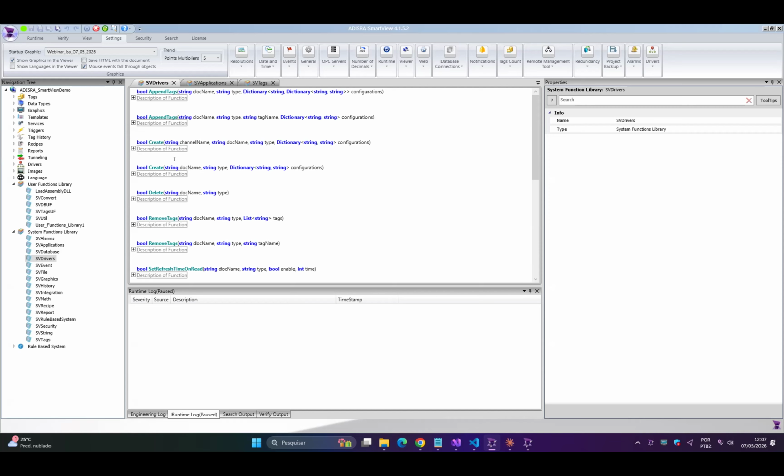to equipment. And also you can create a faceplate as a template to represent that equipment. So we can also have an entire template that creates all the tags, all the addresses, and everything in one object. And it's easy for the developer to just use this object, plug and play. Okay.